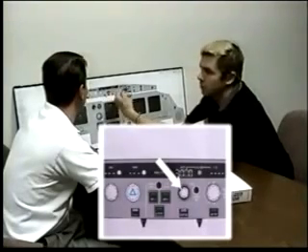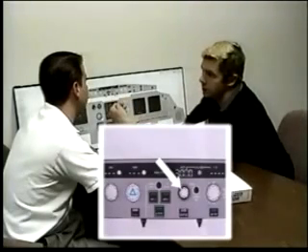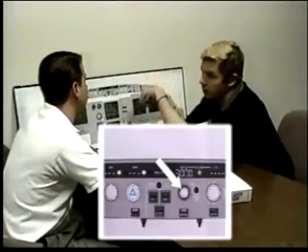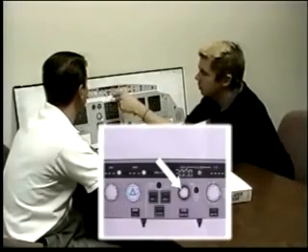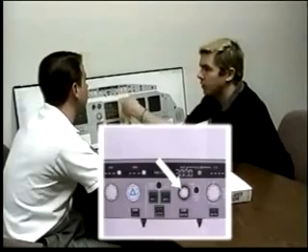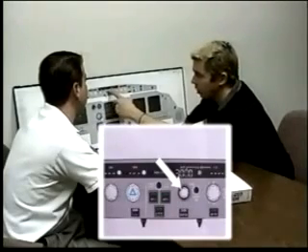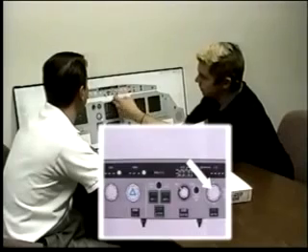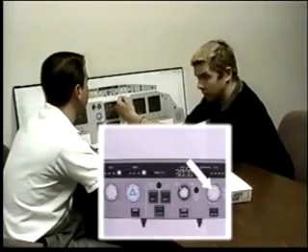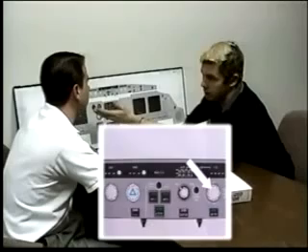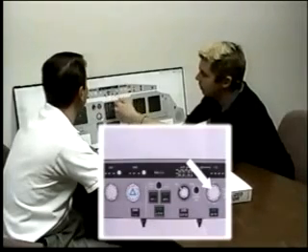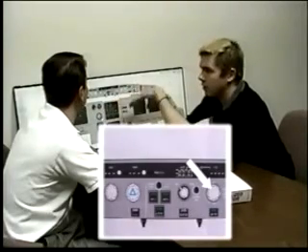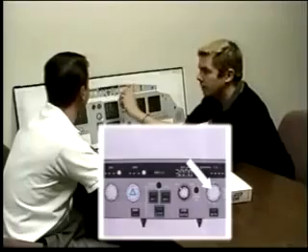Under the altitude, pulling is asking for an open climb or open descent depending on whether the altitude is higher or lower than my current altitude. Pushing is asking for climb or descent mode. Now pushing it only will work if I've got nav mode engaged. And then the last one is the vertical speed knob. Pulling it is asking for a selected vertical speed or flight path angle in track flight path angle. If I pull that, it's going to come up to whatever my current vertical speed is, and then I'm going to dial it around.